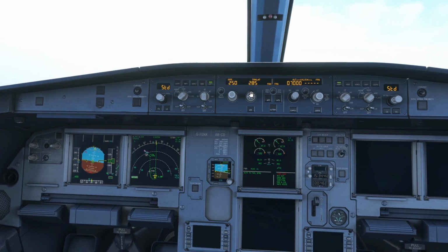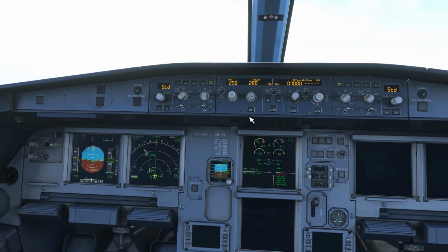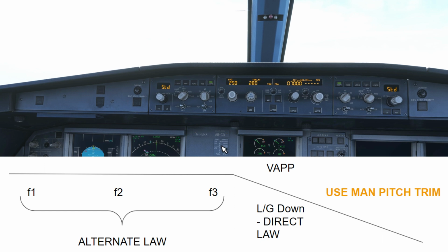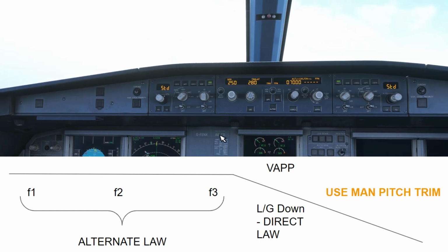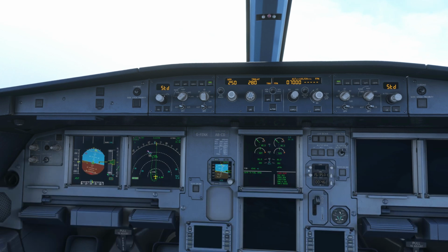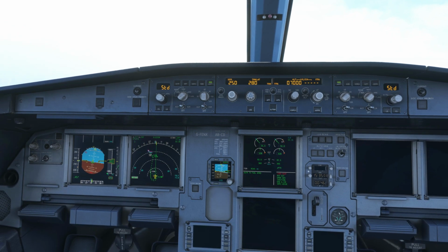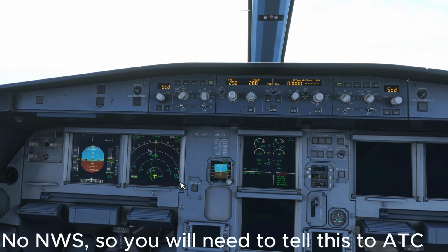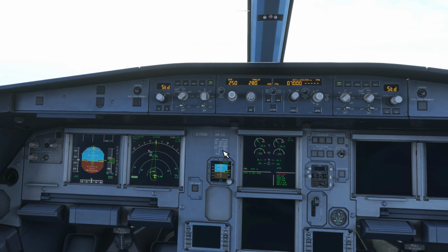For the how part, I will look to fly an early stabilized approach, ensuring I am flaps 3 by the time I intercept the glide slope. Once on the glide slope, and speed is at VAPP, I will call for gear down. The 1,500 foot calls are standard. Once we have come to a stop on the runway, the tow tug will come and meet us as discussed with ATC. That's all understood. I have no questions. Could you press the LS push buttons, and extend the center line?